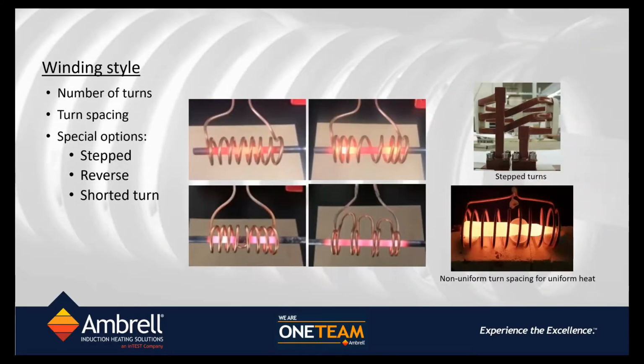Once you determine what type of coil or how many turns you need, the way you wind the turns has a really big bearing on how the heat is produced. The 4 pictures in the center of your screen show the same 8 turns of a copper tube being wound in different manners to provide different types of heat patterns. This is basically the way the coil turns are wound, the spacing between the coil turns. You can affect the same number of turns to give you differences in heat.